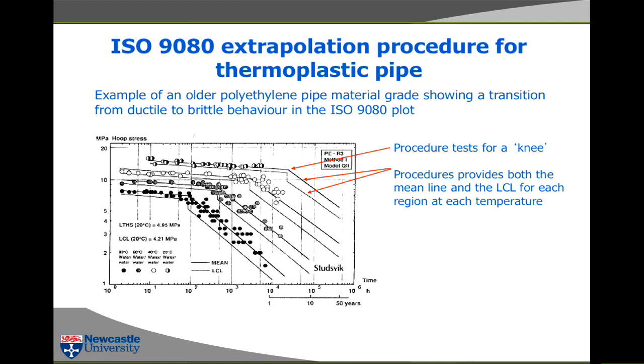And you'll ask yourself, well, how can you plot this line when you haven't got any experimental points? And the answer is, you can plot it because you have the experimental points at these other two temperatures. And you fit it to the Arrhenius relationship. Arrhenius will tell you what it would do up here. So that's given you the ability to observe this effect. So if you're wanting to have a design temperature of 20 degrees C, you've actually got to do measurements up to 80 degrees C. And if you want to go higher than that, you'll have to go even higher in temperature.